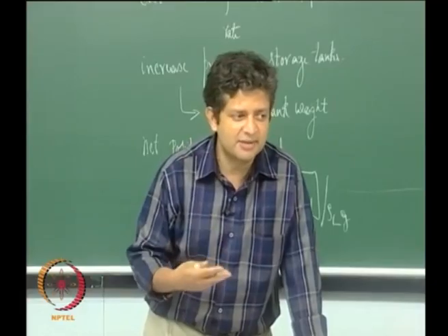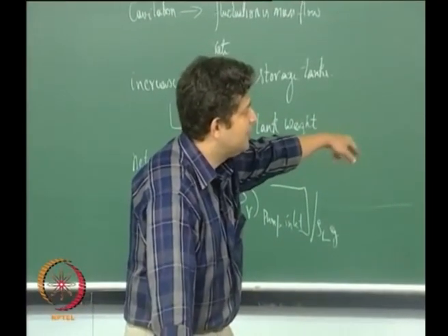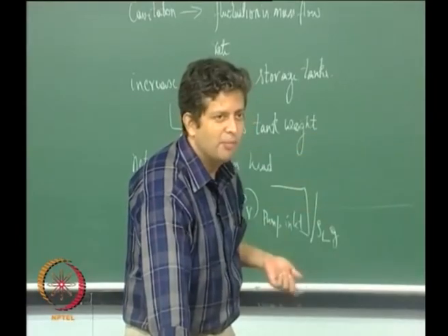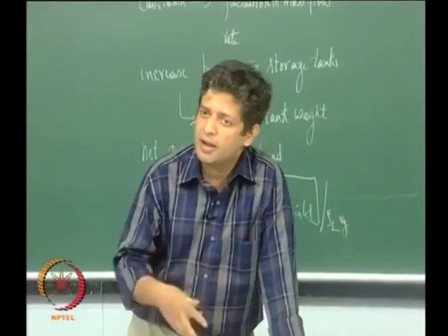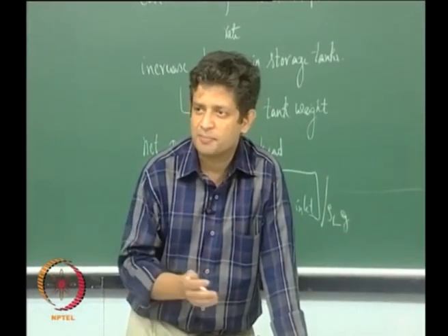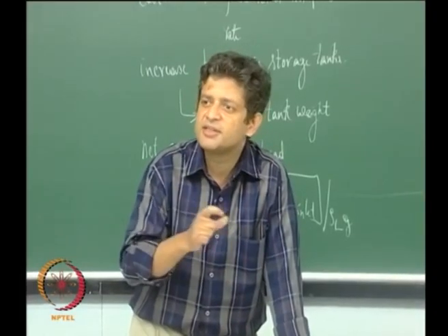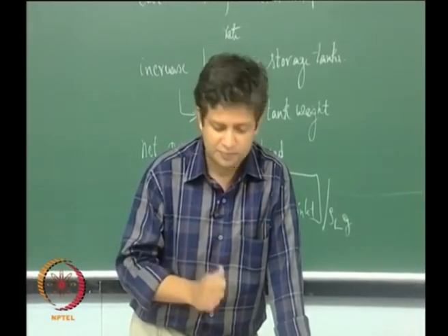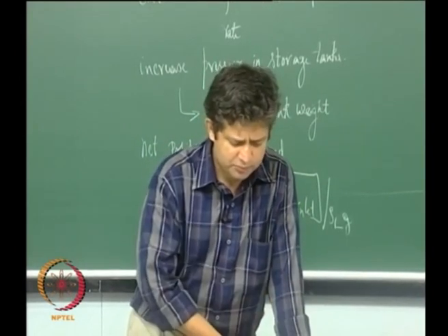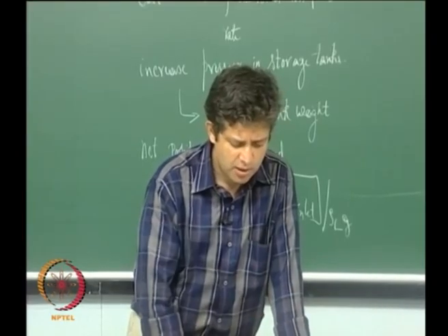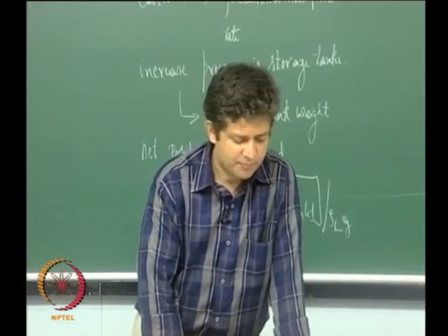This is in a sense the same thing as having pumps in series, but in this case an inducer is some kind of special pump wherein a very small head rise is given, although it is rotating at the same RPM. Okay. The velocity triangles are adjusted such that the head rise given is very small. So, in this way you can overcome this problem of cavitation in pumps.